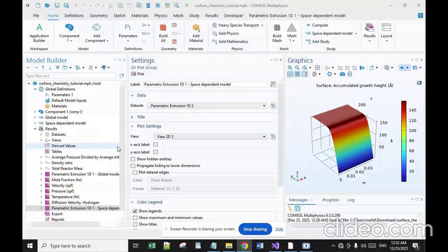And what are the key advantages? The first advantage is high quality: it produces pure, dense, and uniform films. The next one is conformal coatings, excellent at coating complex shapes and internal surfaces. The next advantage is versatility. Works on various materials like metals, ceramics, glass, and polymers. The next advantage is tunable properties, allowing customization for hardness, corrosion resistance, lubrication, etc.